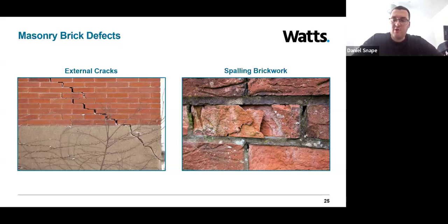There is guidance out there on cracks to buildings. An example would be BRE Digest 251, which typically assesses cracks in low-rise buildings and dwellings, but the theory of that can be applied to higher-rise buildings. This basically states that any crack less than 5 millimetres in width can be filled and may not be of structural concern, but wider cracks than that may need further intervention. This could include helical wall ties, for example. It could include installing an expansion joint to deal with thermal movement, or in extreme cases, it might even involve reconstruction of the wall.